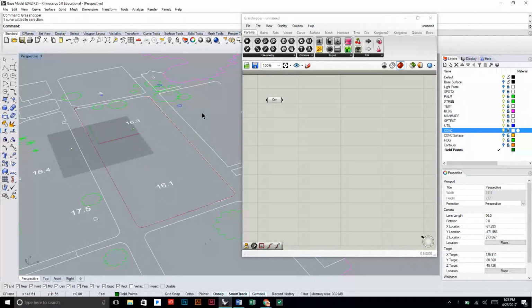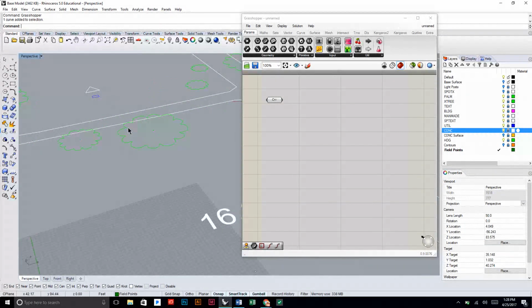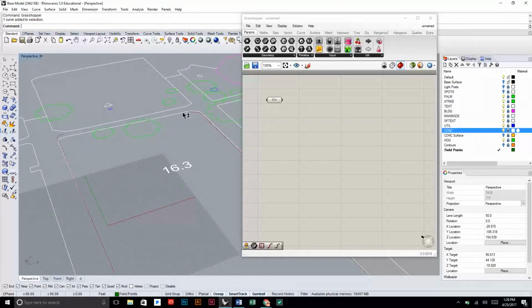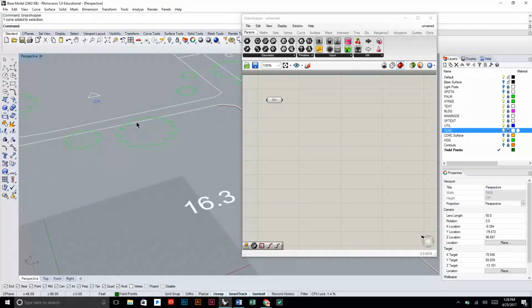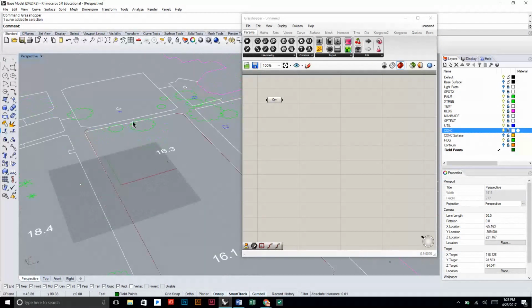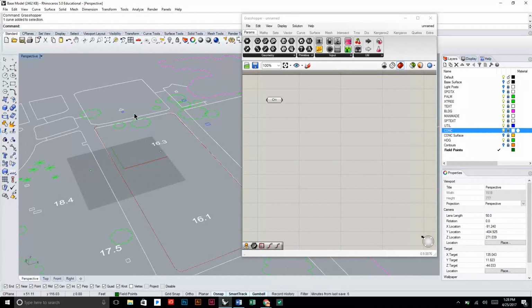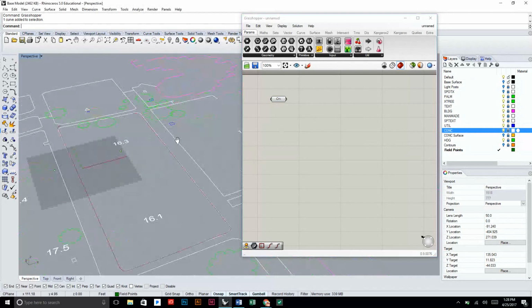So in order for these vector forces to work, you actually have to use an open curve. If it's a closed curve, it's going to create a lot of issues when you try and create a surface from that. So you could really make this curve all the way up until they're barely touching. As long as it's an open curve, it'll work. It's when it's closed that it starts to create issues. So we have our curve here.